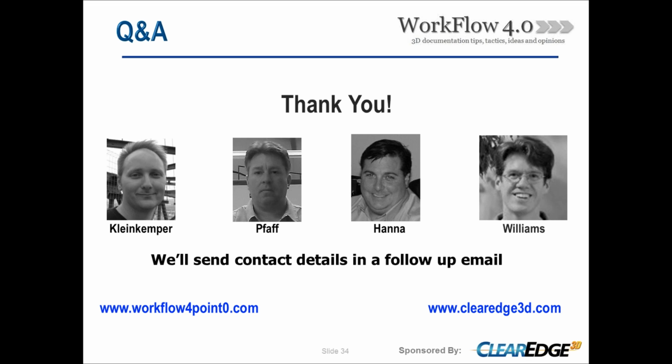So yeah, if you can set up that stuff before you even bring scans into Revit, set it up back in Cyclone, you'll be happier when it comes to the Edgewise imports as well as any future point cloud imports. Yeah, I agree with you on that. We've had to go back and have a secondary model, now that I think about it, because you can only have one of those exist in any model. Once you change that, you do have that problem, but it can be done.